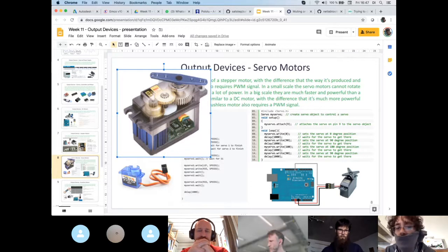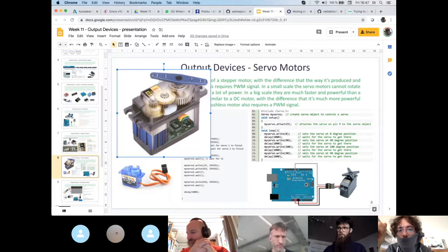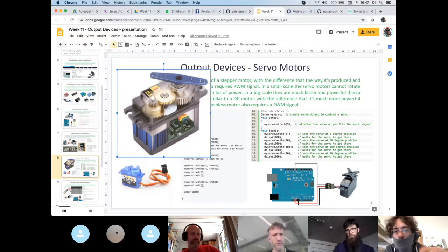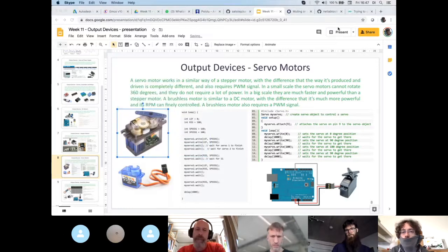Let's say that your CNC is cutting something very hard, or there is an accident and you lost some steps, then the software is able to realize that you lost some steps because of some accident or some losing of the positioning of the motors. And then with the software, you can go back to the original position because you can check with a feedback system where you are. So if you open a printer, guys, nowadays, they have these optical encoders on the back of the motor that can check the position.